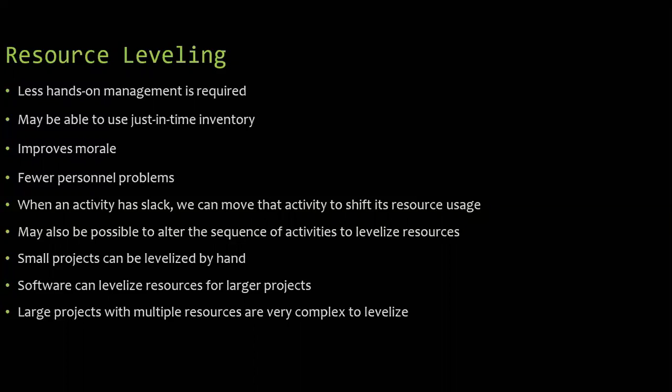For that 5 days delay, you cannot start your slabbing work on 10 July itself, because whatever is necessary for that slabbing work is not yet completed on 10th of July. It should be completed on 15th of July. So that's why we are saying here that we cannot move the activities to shift the resource.